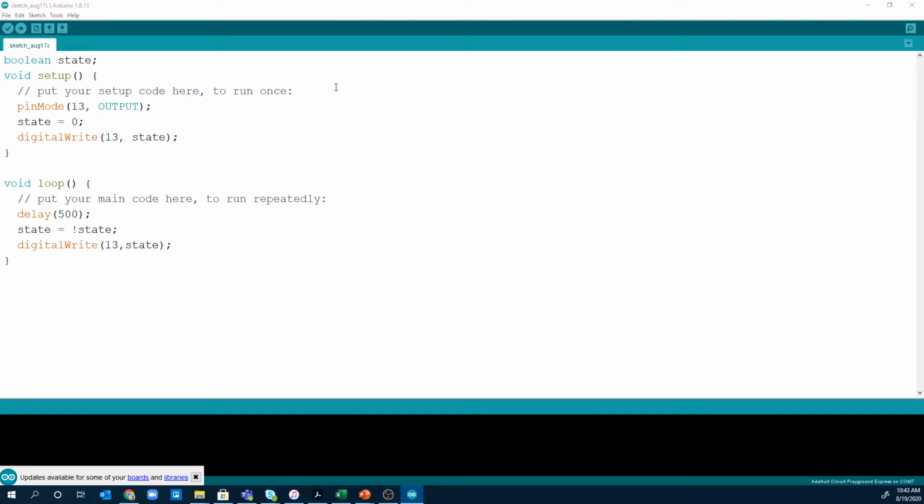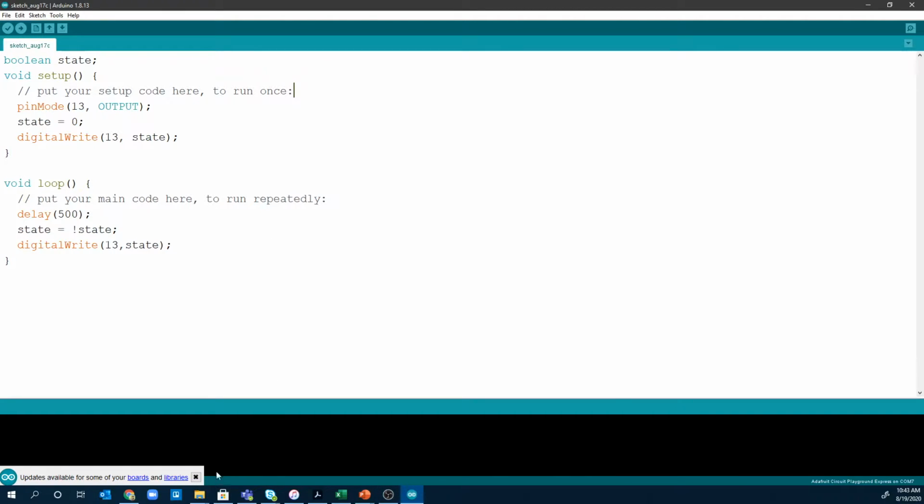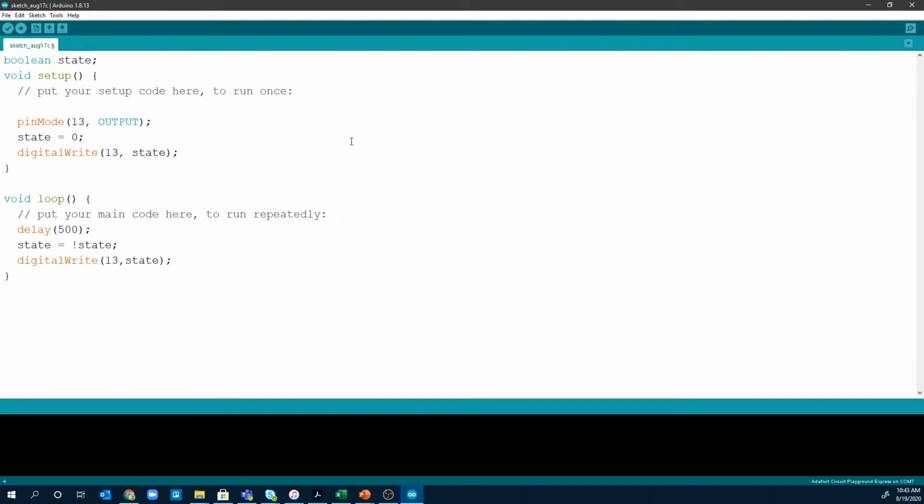The first step in using anything serial on Arduino is to go ahead and start the serial port. To do this, you simply type Serial.begin. You're then going to put 9600 in the parentheses. This is what's known as the baud rate. This is the speed at which the data will come from the board back to the computer. There are some standard baud rates, although 9600 tends to be the standard for Arduino. You can change it to whatever you want, but most documentation you see is going to use 9600.